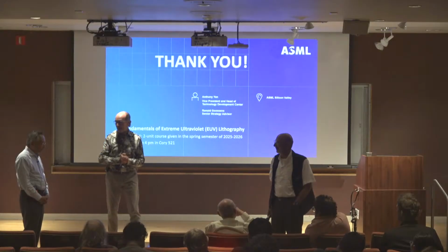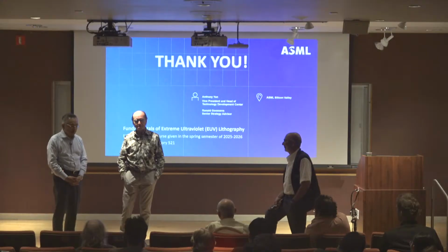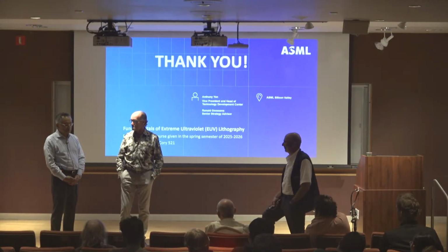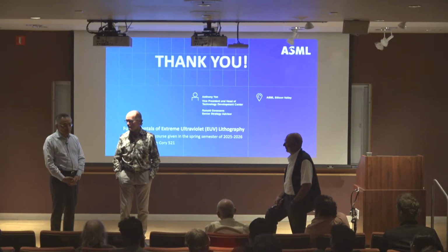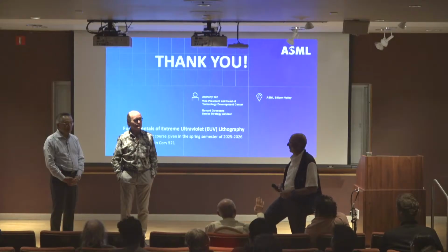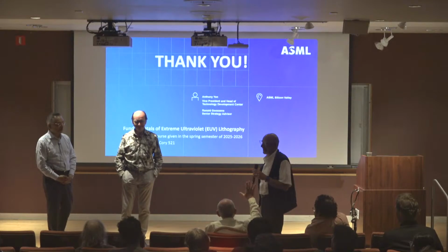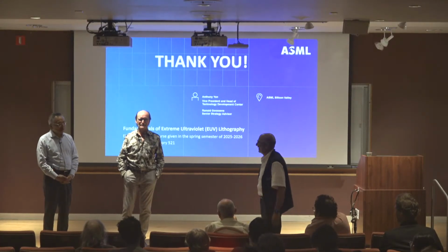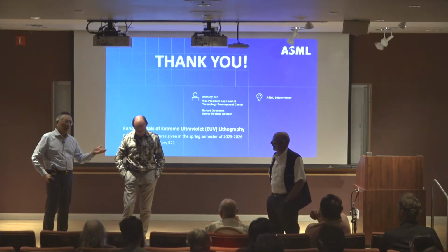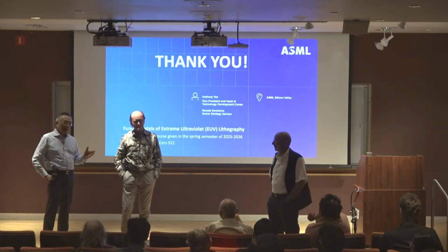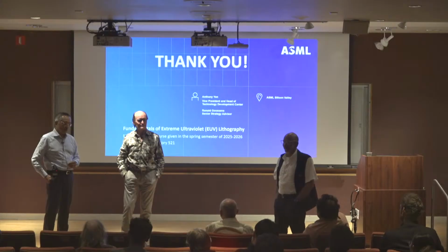Yeah, well, historically, Ronald was right, down to maybe 90 or 65 nanometers. That's the half pitch. When you say 65, the half pitch is 65. But nowadays, no, it's just a marketing name. I hope that this is not recorded. Don't want my customers to hear this is just marketing. They know. So cut this part out of the recording, okay? No, it is an improvement over the previous generation. Yeah. But is it 2x the transistor density? No, those days are over.